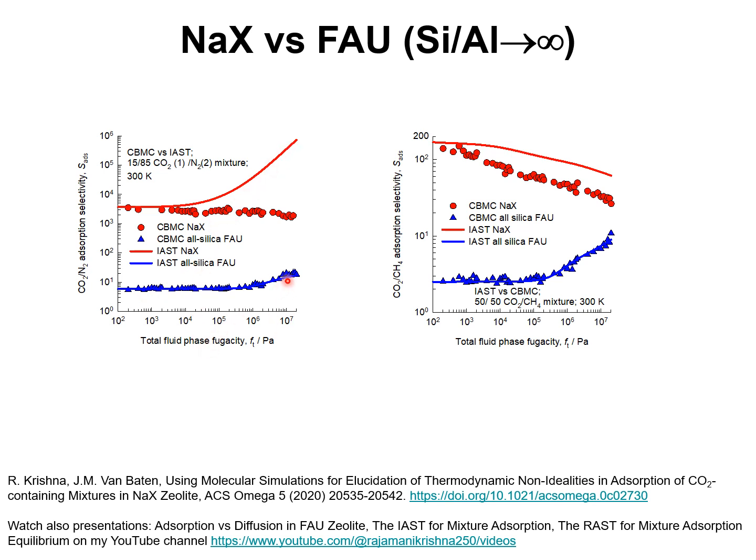For all silica FAU, the IAST is in excellent agreement with the CBMC simulated data, whereas for NaX zeolite, the adsorption selectivity is severely overestimated.